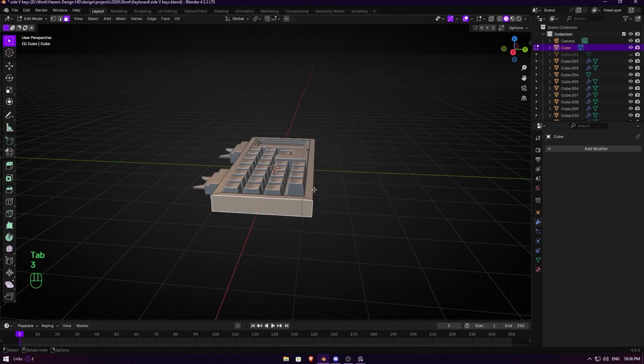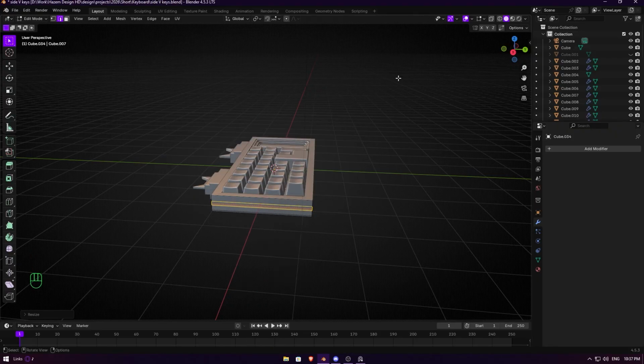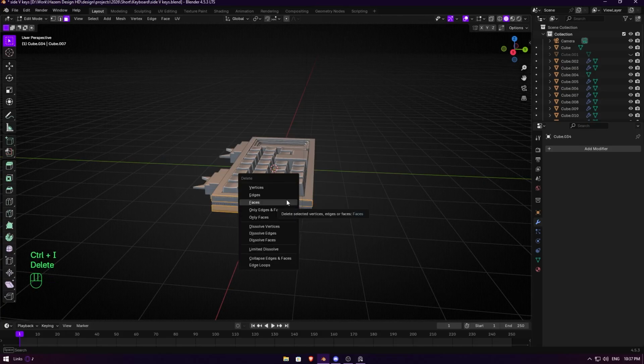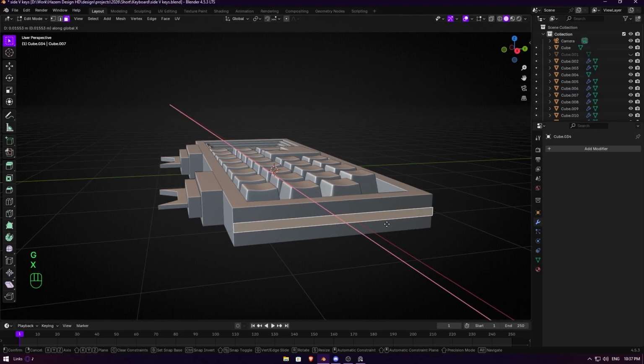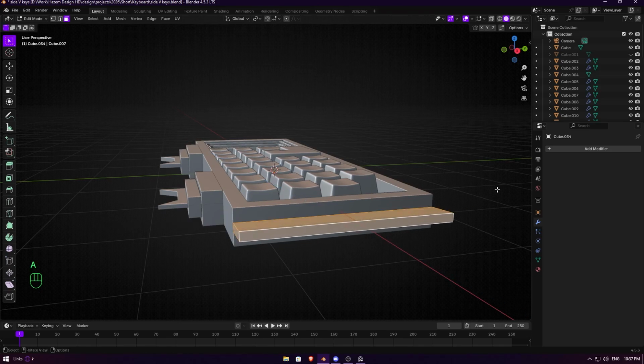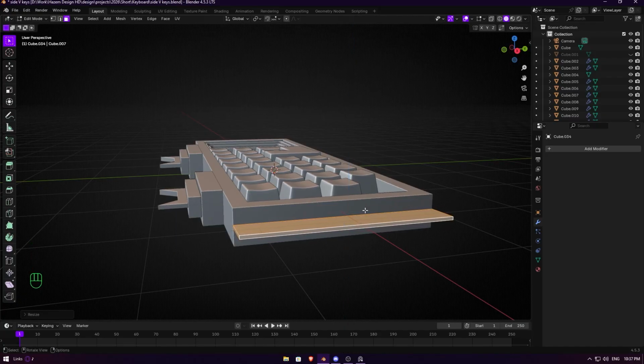So we're gonna go with this one and go with Shift E again. B to separate. Then go here with one loop cut along like this. I think maybe Control I. Select face and Control I. Then X or delete and delete the faces. So we can pull this out a little. Something very tiny. And extrude it. Select everything, S and Z to scale it down in the axis like this.